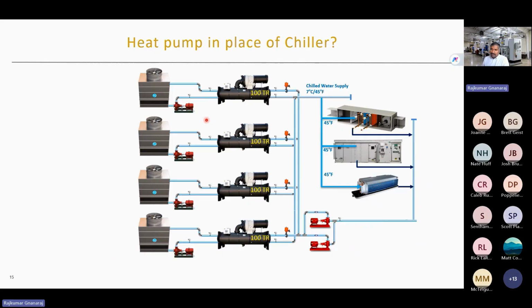We have seen in some places where they are coming up with a brand new facility and they are planning to go for 4 chillers, and then maybe a steam-based hot water system or an electrical heater-based hot water system, instead of going for 4 chillers separately and then 2 steam boilers or 4 gas-fired water heaters for heating, and simultaneous chillers for cooling.